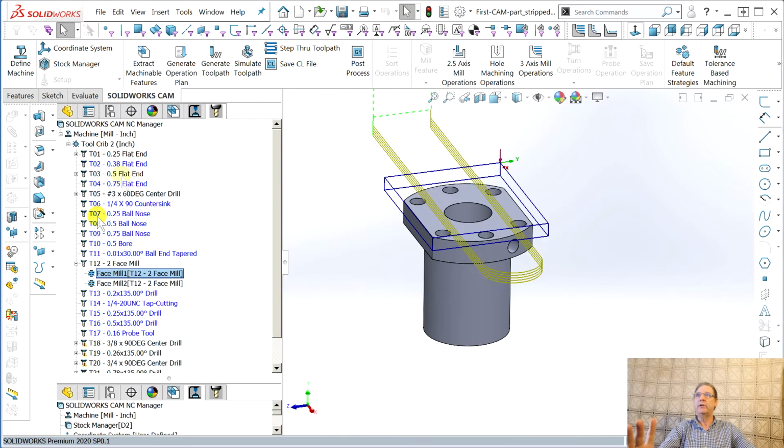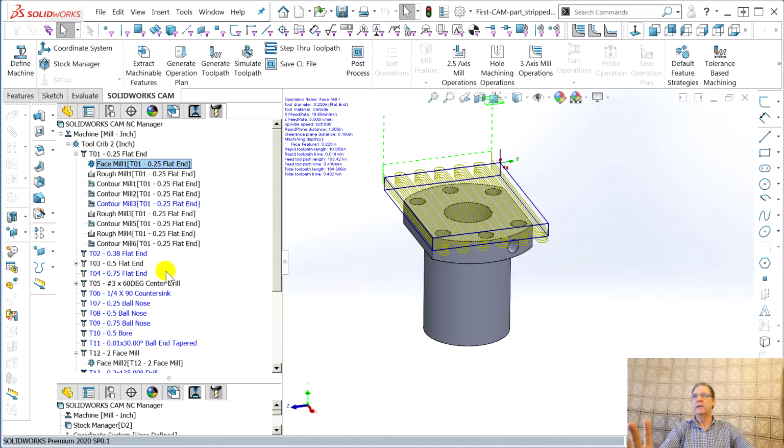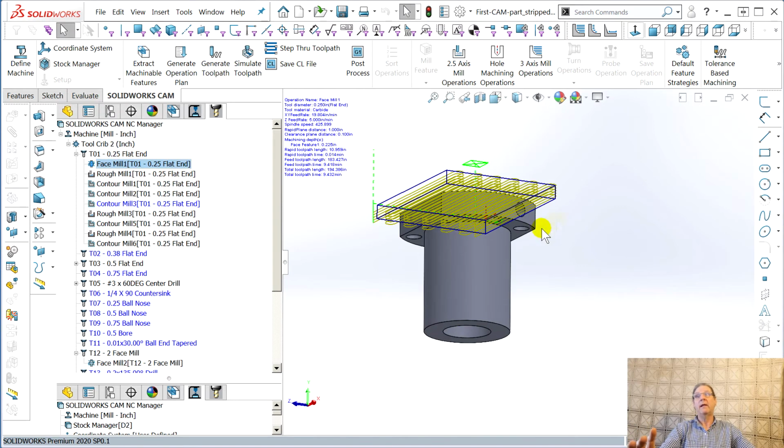You can take it here in the Tools tab, up here, SolidWorks Tools tree, and let's light up. There's a 1/4-inch end mill, which is the only tool I want to use in this little Avid. Come up here, drop it in. Come up here. See? Automatically, it changed the tool paths for a 1/4-inch end mill. That, I think, is pretty cool.